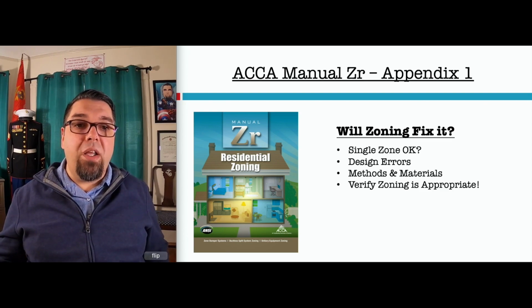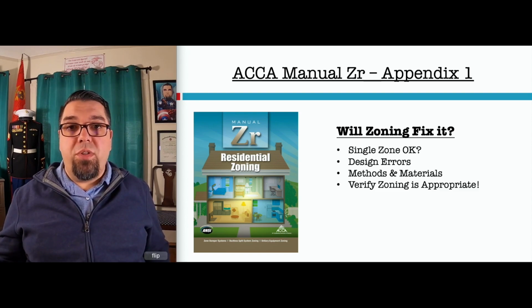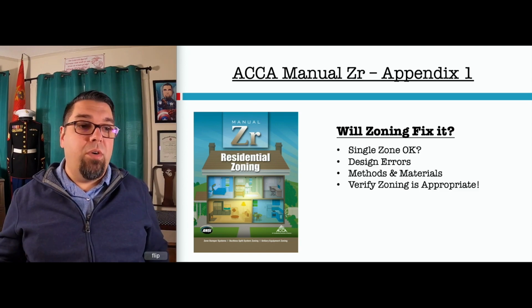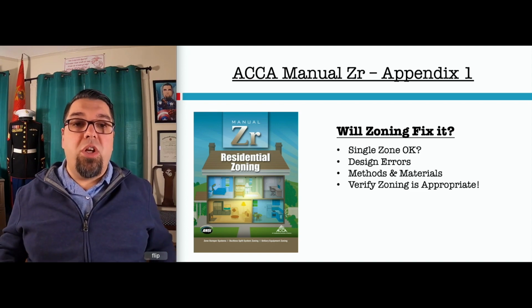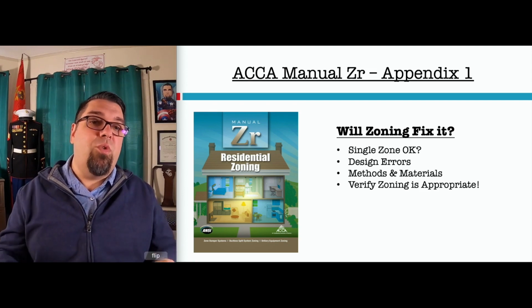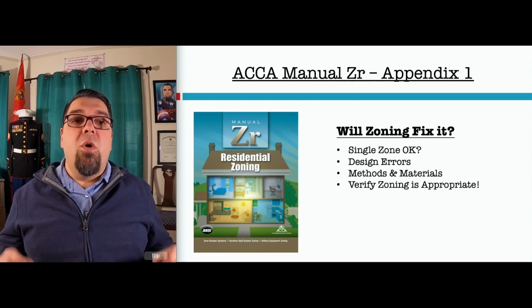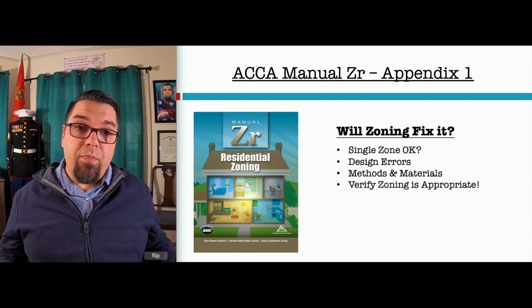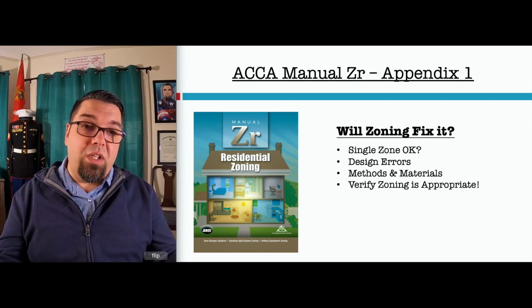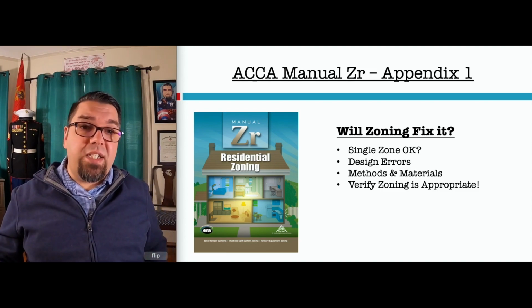Everybody that buys a house, that lives in a home, finds comfort issues, whether they're there for one day or 10 years. So if you ask in the process, do you have any rooms that are uncomfortable? And you start to figure out that these are the ones furthest away from the space. You have a single zone system with one thermostat on the first floor, big temperature differences across floors. You're much better off zoning with equipment and then possibly zoning the ductwork off of that equipment if you need to.